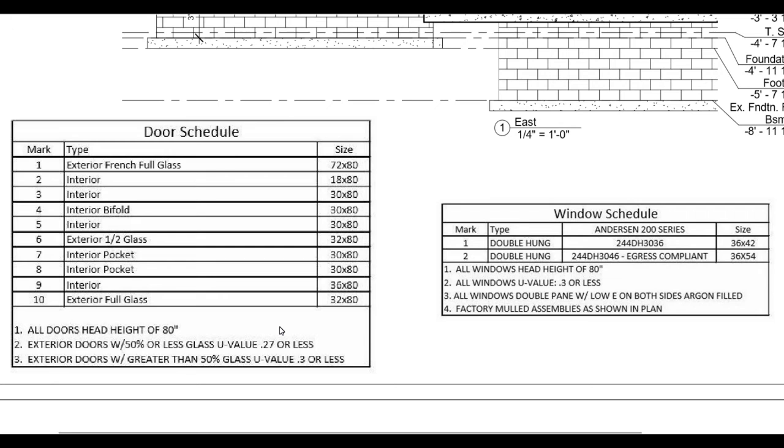An example, insulation would have a high R value, which would be good, and something like steel or stone or brick is going to have a very low R value, which is not going to resist heat transfer. So that's bad for energy efficiency. If I have a high R value, that's good.